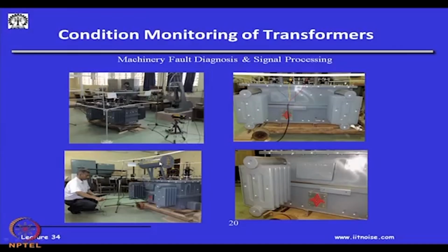And you would have heard of scenarios where there was a power outage because of a transformer burst. Why did that burst happen? Because the transformer was dry, the maintenance crew had not ensured that the level of the oil was there, and that is the reason why transformers burst. So, in our laboratory here, we are trying to measure the vibration of a transformer.